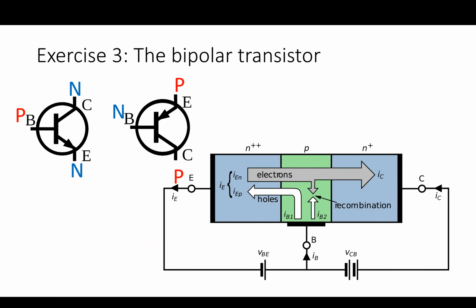Let's look at a much more interesting device here, which is the bipolar transistor. The bipolar transistor actually looks like a pair of diodes back to back. So here's N-doped silicon full of electrons, P-doped silicon full of holes. And so this then would look like a regular diode. And this way around, the arrow would look as though it was going this way. This would be what would make the current flow. The electrons went this way.